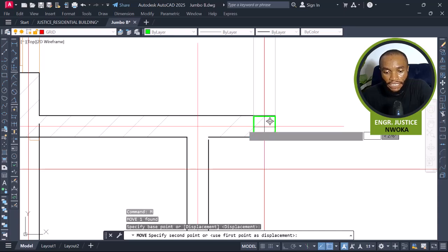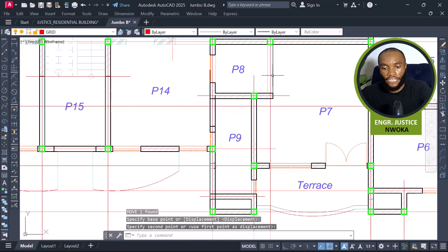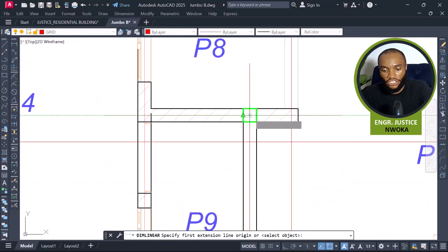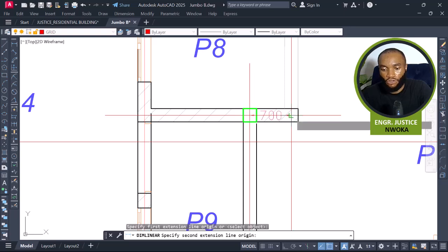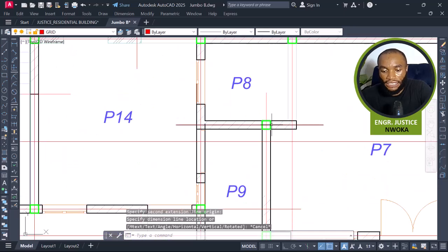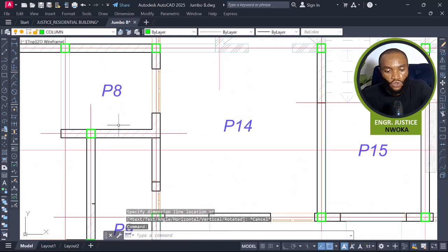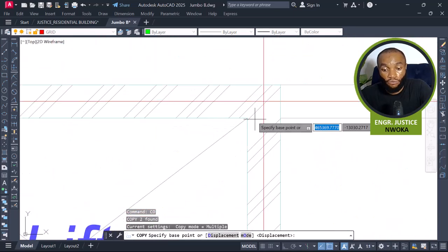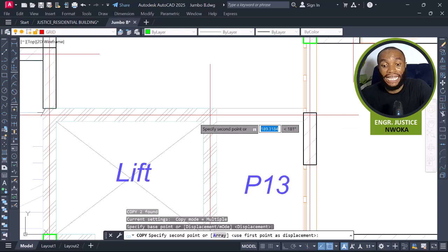Place this here. Yes, we can have this cantilever beam to carry this other smaller beam here. This beam length is very small, so it doesn't have much of an issue, and it will not consume much rebar. This is 700, that's fine. So with this now, we can see that these two columns will be hidden inside the wall throughout from the foundation, which is from the ground floor down to the fourth floor.